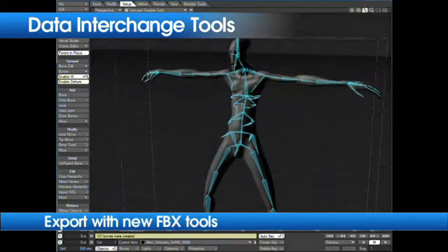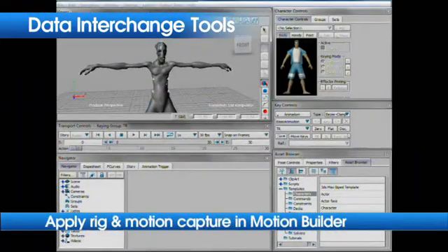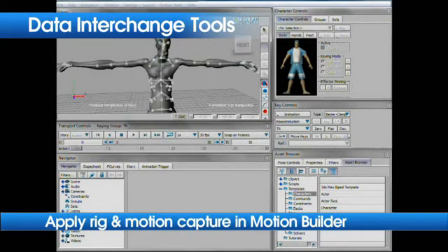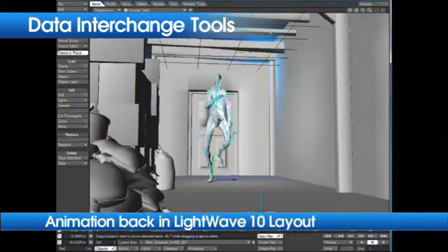If there's one true fact in a modern effects studio, especially at the television level, it's that we're having to deal with many packages to get the job done. The turnarounds are just that fast that we have to run to whatever will get the job done. And one of the things LightWave 10 has done for us is they've really rewritten the input-output suite of the program. The combination of the MDD format with FBX, Autodesk Geometry Cache, and Collada allow you to have so many options for getting data into LightWave and exporting data out of LightWave to any pipeline. Just that it's there, ready to go. Bring in something from Max, bring it in from Houdini. Okay, now we're ready to render in a very solid rendering package that LightWave offers.